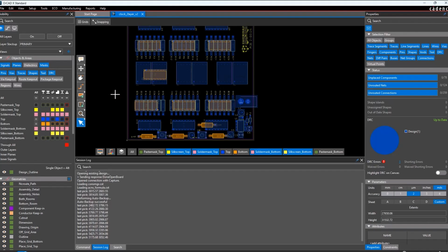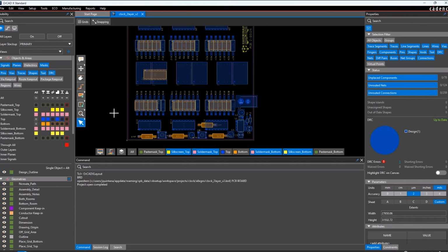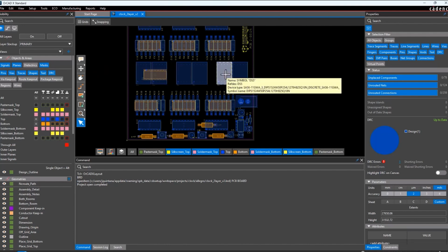And so the capability is there, it's included with the software, and all it really needs to be done in Presto for the translation to work properly is defining the stack up, the number of layers that are going to be on the PCB, getting the thickness down, and then placing the critical components.